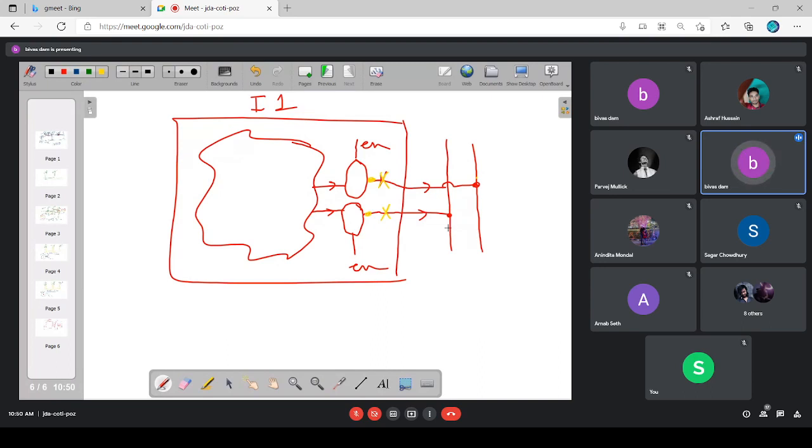And I know that if there are 4 input devices, only one input device will get enable input 1. The other 3 input devices will get enable input 0. So for those 3, the corresponding final output stages will isolate themselves from the external world. Now only that particular input device which is getting the enable input 1, internal to the final stage tri-state TTL logic family is getting Z equal to 1 or enable equal to 1, the corresponding output will be a valid logic 0 or valid logic 1.